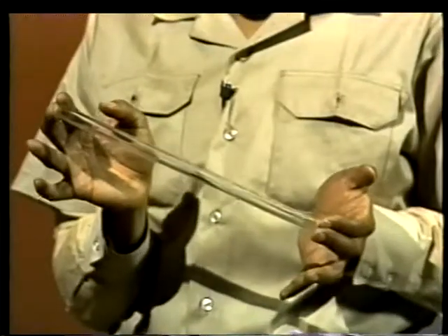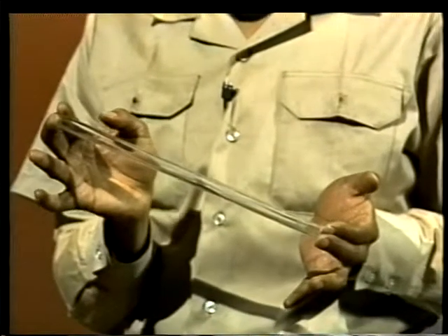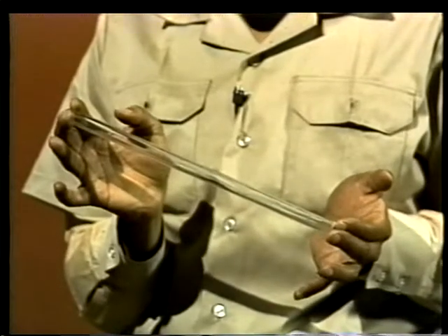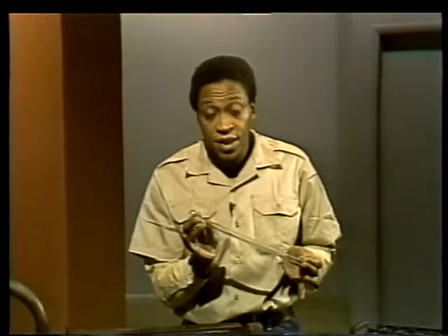Check to make sure there are available replacement parts. You may need new seals. Also be sure that there is replacement glass on hand, because there's always the chance that the old glass will break. When selecting replacement glass, be sure that it is rated for the correct temperature and pressure. All tubular glass is not the same, and it is vital to get the right glass for the conditions. If there is none available, check with your supervisors.